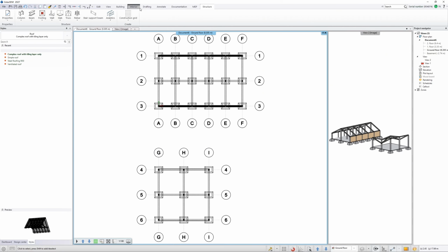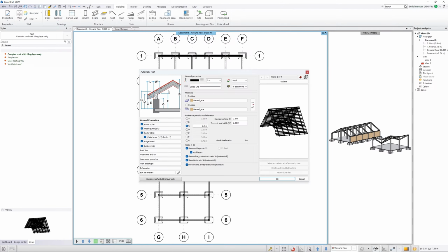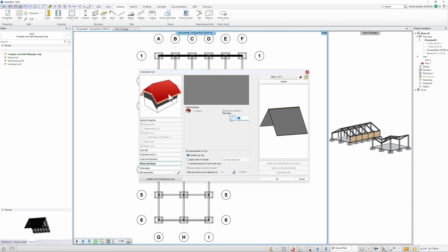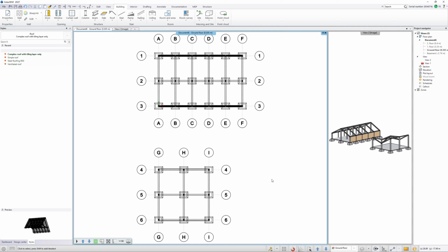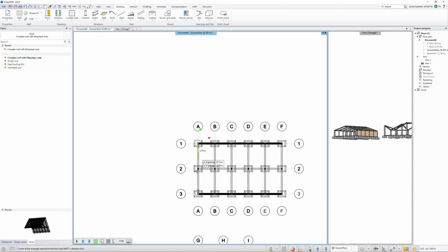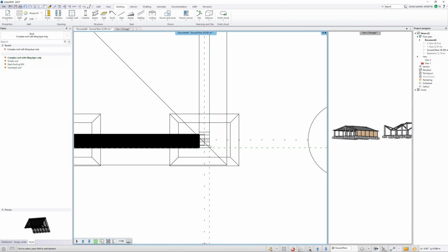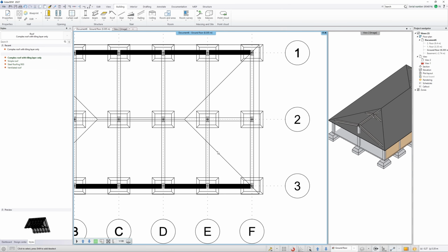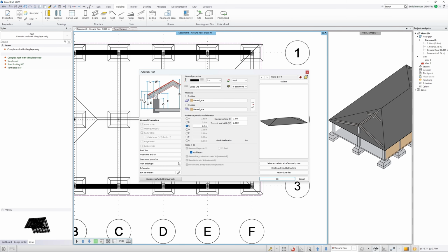The properties of the roof can always be customized according to the specific project. In the Properties dialog, we can customize the structural elements of the roof, set the materials to be used, and specify the angle of inclination of each roof plane. Adjust the angle of inclination to the already created frame structure so that the two surfaces will fit together perfectly when placed. Once we have finished specifying the roof settings, we can place it in our project by drawing the desired shape. The settings of the roof planes can be modified after placement, allowing us to always create a shape that meets our specific needs.